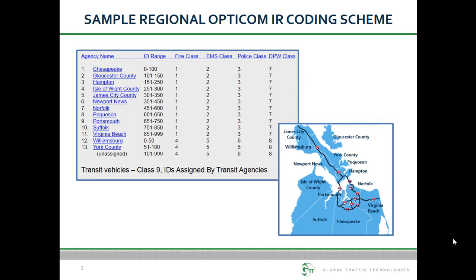In using this technique of combining vehicle class and vehicle ID to achieve 4-digit codes, it is important to realize that this likely eliminates the option of using the relative priority feature, which also allows different classes of vehicles to have different priorities within the IR system. It also eliminates the ability to set different activation points or range settings for different classes or types of vehicles. However, it may be possible to still code the vehicles in such a way to be able to use these